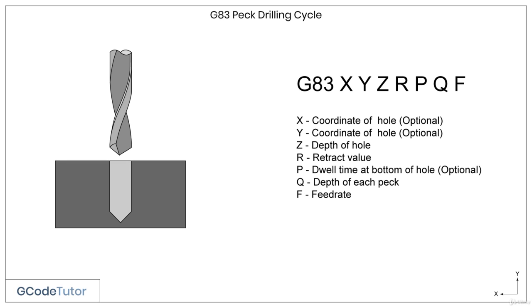So we've covered a standard drilling cycle. Let's have an in-depth look of how a Peck drilling cycle works using the G83 command. The standard FANUC G code for a Peck drilling cycle is usually G83. This can change depending on the different types of controls your machine has, but using the FANUC standard, this is normally the G code that we use.